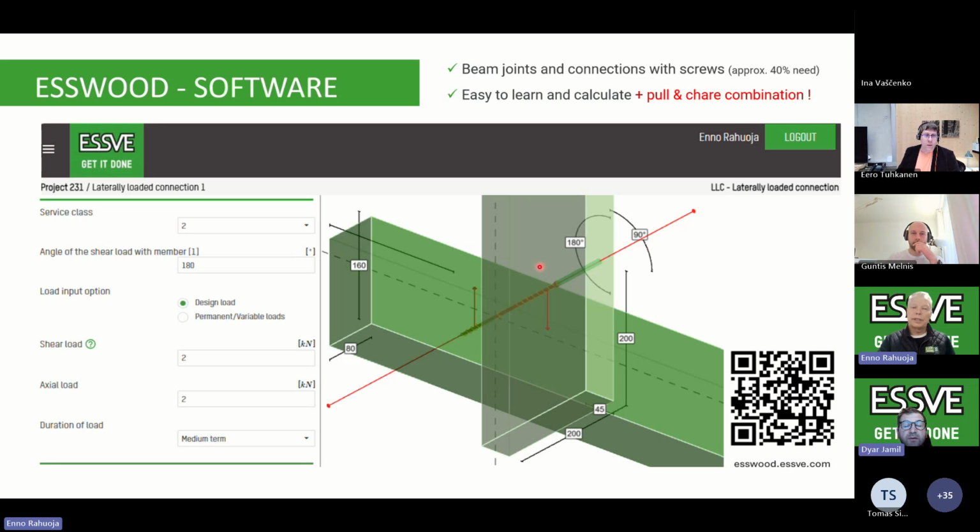Yeah, and in the sample I will send you, I have even set the fastener to 80 millimeters. So you can also set a distance, how deep you want to go with the fastener. So if you have a hidden type of fastener like ETT or full threaded or cylindrical headed screw, then you are able to dive also into that rafter.